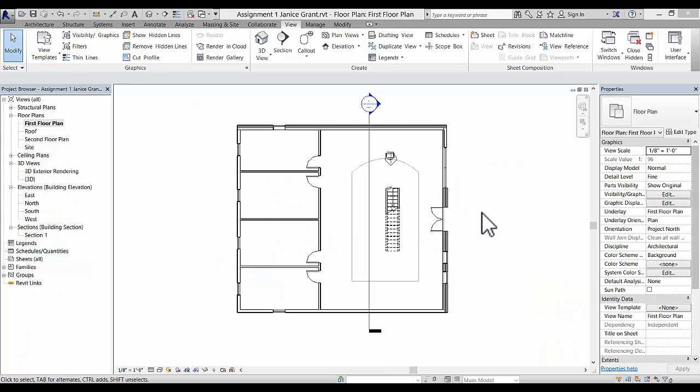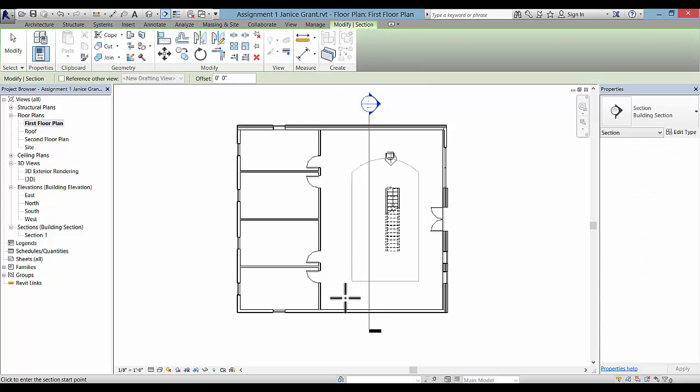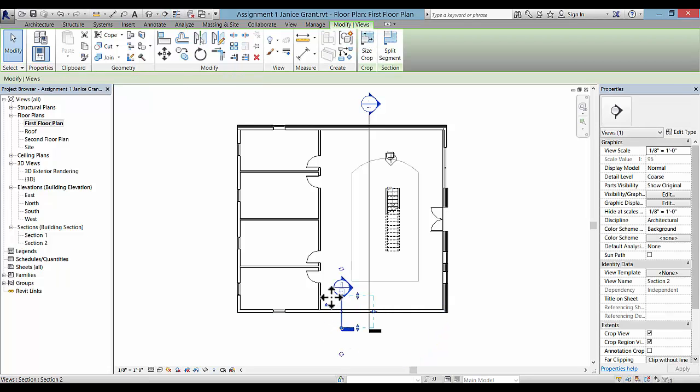The first thing we should do is open up one of our previous projects, or maybe one that you're working with in another class, and go to the first floor plan so that we can create a wall section. We've already created this building section that we worked with in our assignment 1 and 2, combining that big picture drawing. So now we can go to the first floor plan of that drawing, or like I said, a different drawing if you like. Go to the View tab and we'll pick section and just draw here a wall section through this wall here, looking towards the right here.